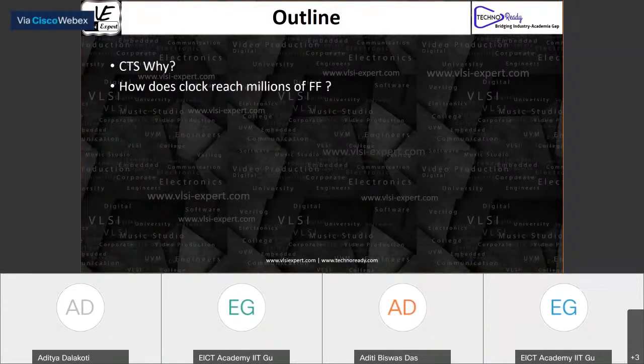During ASIC design, how are clock tree buffering and all predicted and done before fabrication? Okay. So clock tree design is actually done a lot from experience, honestly. By experience in a given technology, you have a decent knowledge of, okay, if my design is a few millimeters, how many buffers are expected to be put in there for a given clock frequency, and it takes time to get that experience developed.